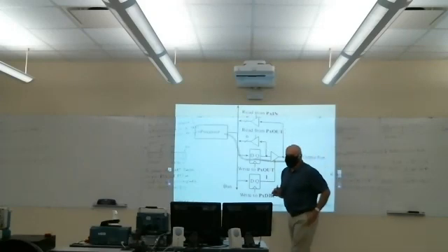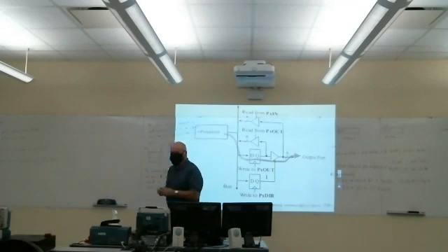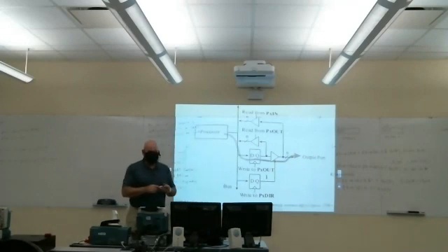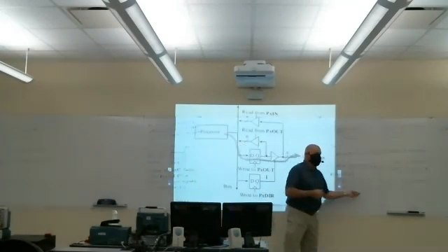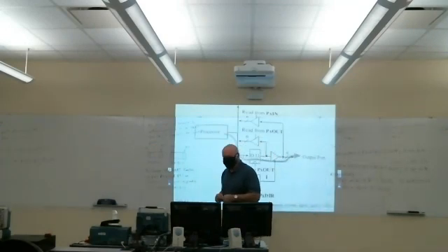Okay, so again, it's got some extended capability that I don't think we'll take advantage of. We'll primarily just be reading from an input pin, like on the previous slide, and then writing to an output pin. So we'll talk more about this next time, and then actually get into some code where you should be able to turn some LEDs on and off on our boards next time. It's just a few lines of C code or corresponding assembly.